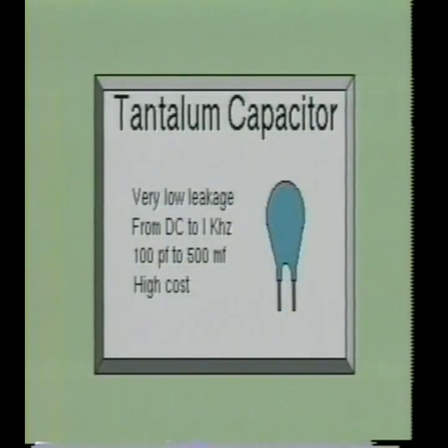This is a tantalum capacitor. This capacitor has very low leakage and is used in frequency applications ranging from DC to 1 kilohertz. The size of this capacitor will range from 100 picofarad to several hundred microfarad.